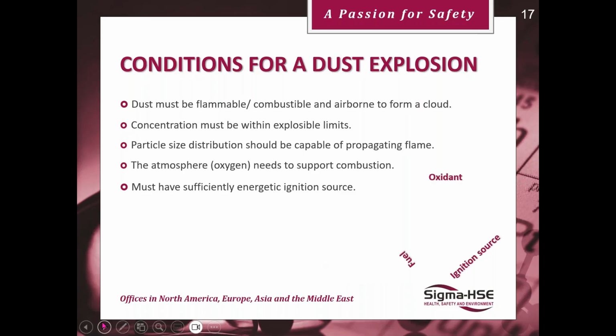When it comes into the dust cloud, the concentration must be within explosible limits. Unlike gases and vapors, there are no UEL, upper explosion limits, for dusts, mainly because you generate the dust cloud, which may be extremely dense, but over a period of time, the dust settles. The most important value here is the lower explosion limit, or MEC, which we'll talk about later.